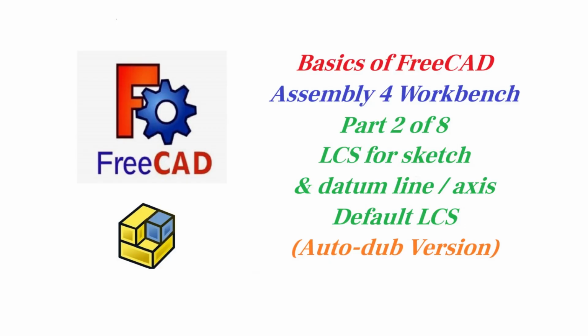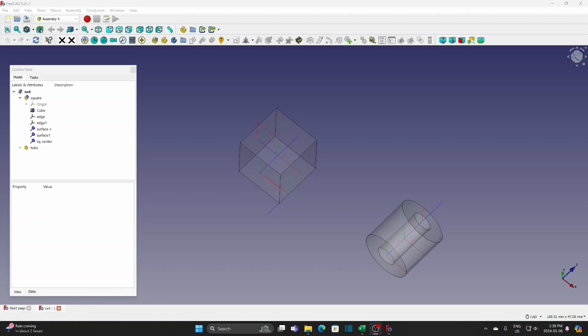This was created by FreeCAD 0.21, but the operation of Assembly 4 is basically the same in the latest version. Part 2, LCS for Sketch, Datum Line and Axis. Default LCS in Assembly 4. Besides the 3D objects, you can also add LCS to Sketch that could be used for the mechanism of an animation.